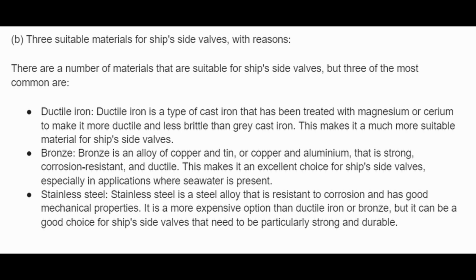Or bronze. Bronze is an alloy of copper and tin, or copper and aluminium, that is strong, corrosion resistant, and ductile. This makes it an excellent choice for ship's side valves, especially in applications where seawater is present.